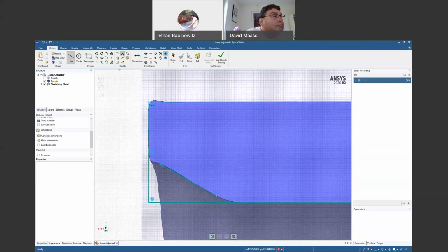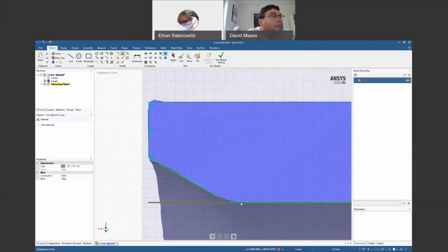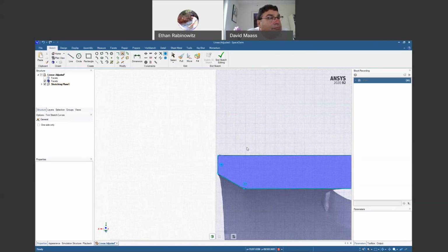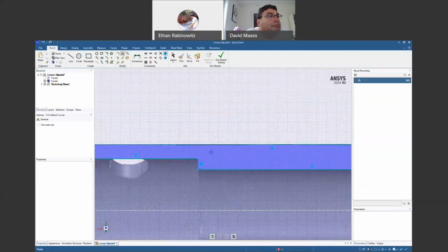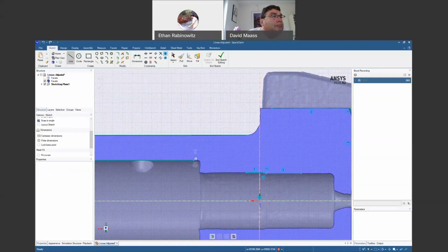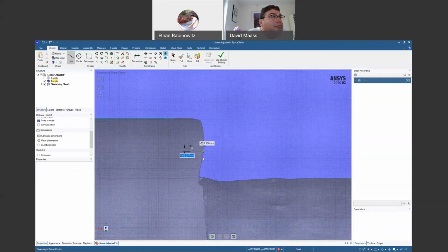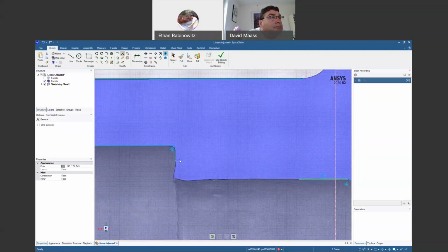And then it's just a matter of trimming. Now with the trim tool, if I click down here, it trims to that side. If I wanted to trim up here, then I click on there. So it's kind of gesture based on where you interact with the model. All right, so we did that line. Now we'll grab the line again. I'm guessing that based on artifacts near edges, somewhere along here is a little more reliable. So I might just go up like this, just making sure I get that 0 value. That's all that's really important here. But again, I could set my horizontal constraint on it as well.